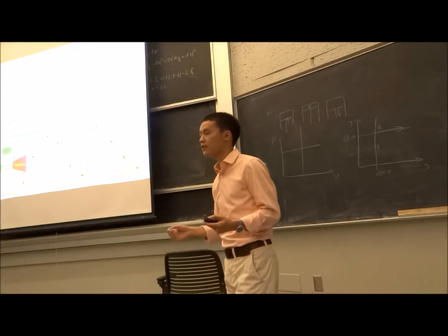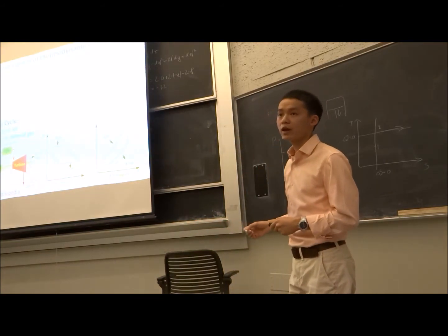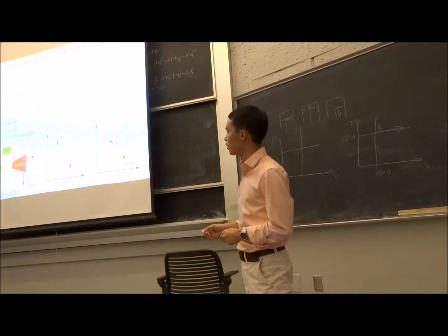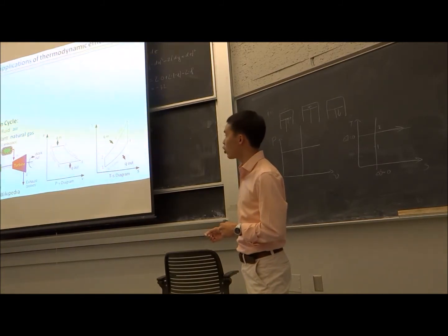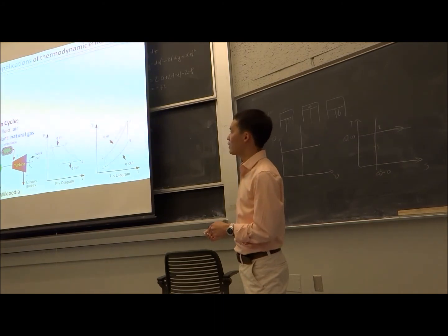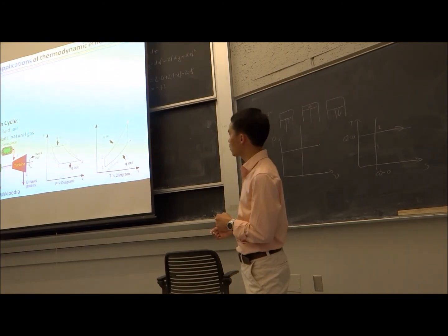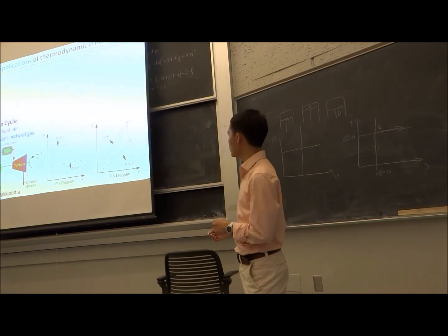And natural gas may be the intermediate source of fossil fuel that will see growing consumption over the next decade or so. So the way we use natural gas to generate electricity is this process where fresh air comes into the compressor. You compress it isentropically from 1 to 2. You see, isentropic is just vertical, go this way. And then you inject fuel, natural gas, and you combust it. You have this very high pressure and temperature gas after this constant pressure process, 3. And then this high pressure and high temperature gas will go through a turbine, rotating the shafts, providing electricity.